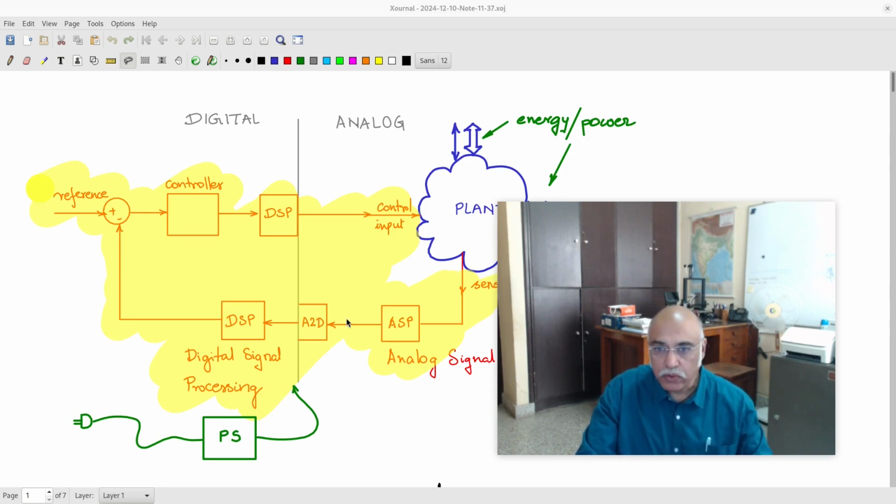Now after the zero and span circuit, you can take the signal towards the A to D, but before you give it to the A to D, you need to pass it through a filter. And after the filtering, you can give it to the A to D for converting the signal into the digital domain. But why do you need the filter? The filter is called anti-alias filter, and as the name suggests, the filter tries to remove aliasing.